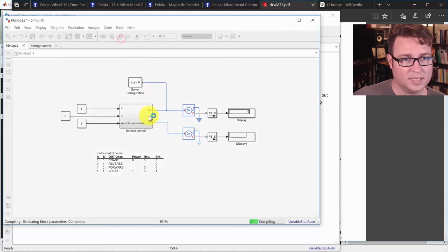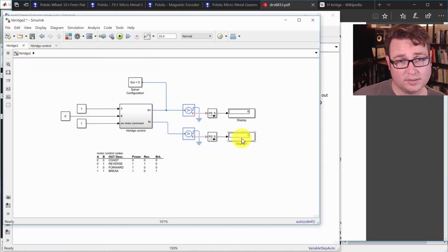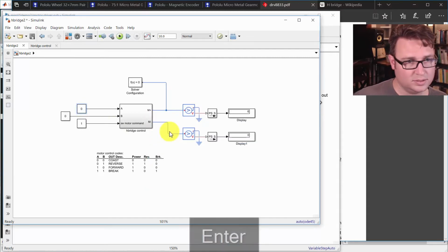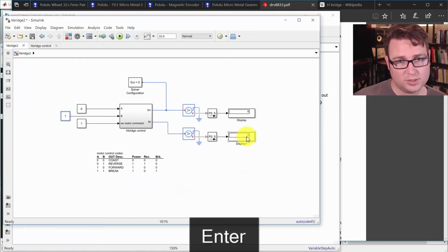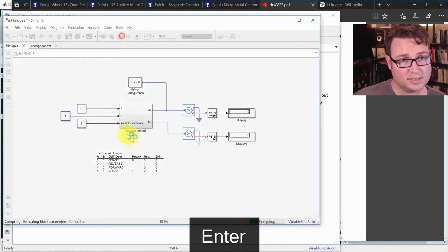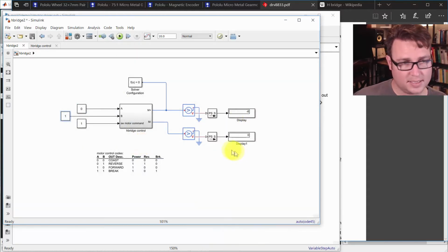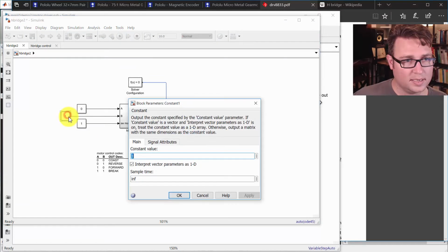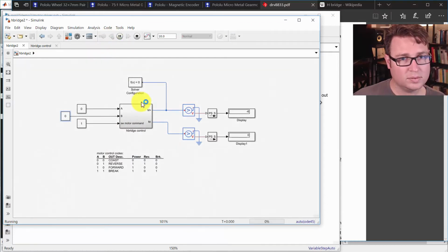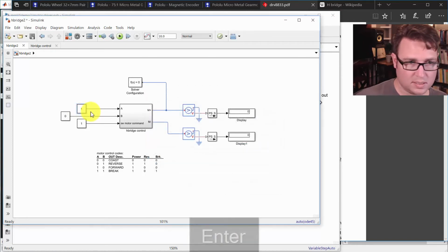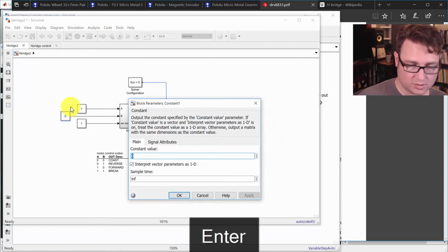and see what the other side is. We connected it to ground, so we expect it to be ground. So let's try 0, 1, which is reverse mode. And this should be 0, and this should be -6 this time around. And it is. Okay. Now 0, 0 should kill the motor command and put us in coast mode, which it does. And 1, 1 should put us in brake mode,